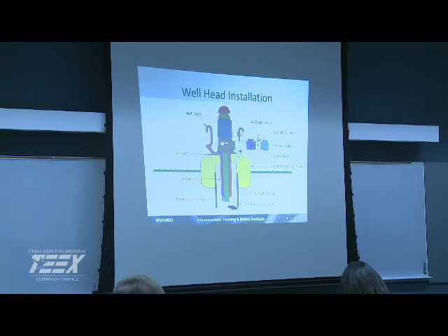So just a quick diagram. We have our pump column, we have our surface casing, need to have it properly cemented in. We need to have a sealing block so we don't have contaminants filtering right down from the surface. We've got to be able to vent our well because as we're running it, we're having pressures changing in there. This is showing a vertical shaft turbine here. The motor is up on top, and you have a shaft that runs all the way down. Normally those are the big wells. If you run small wells, it's mostly submersibles. Those are the most common. So you've got to have relief. You need to have a check valve so you're not pulling a siphon and then flowing back in. So you've got to have air relief and stuff. And you've got to have some way to meter what you're pushing.